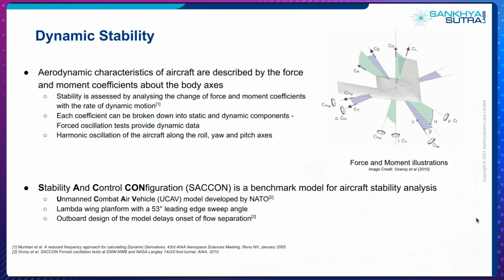So dynamic stability itself is a very important criterion when you talk about aircraft design, right? The majority of your design workflow is driven by the stability of your aircraft, and basically the way you assess these dynamic and static stability is through analyzing the force and moment coefficients that are obtained when you decompose the flow over the aircraft itself. So the dynamic stability is assessed by analyzing the change of force and moment coefficients with the rate of the dynamic motion.